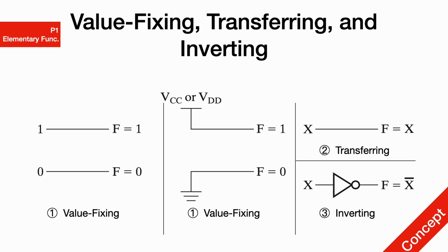Right in the very middle, this is something that you would likely be seeing inside LogicWorks. This is referring to using the actual physical components to assign values instead of just writing down the mathematical circuit diagram. On top over here, you have VCC or VDD. These sources would generate a constant voltage in a high voltage area, which would result in this value being interpreted as positive. Inside LogicWorks, you can find this as a plus 5 volts circuit component. You can directly take and use, I believe, from the Pseudo Device Library.